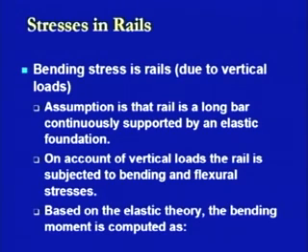Now, why we say it is an elastic foundation is that whatever load is coming from the top is obviously going to create some sort of deflection in the system. Now, when there is a deflection in the system, then this will go down by some amount, but as soon as the load is removed, it comes back to its normal condition, and that is where the elastic foundation assumption remains valid.